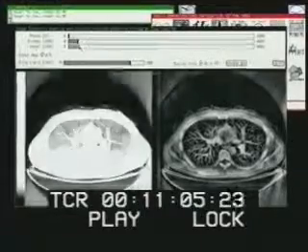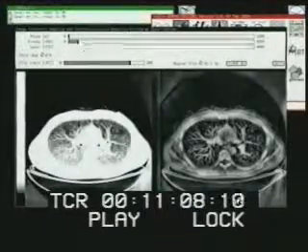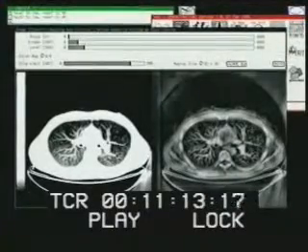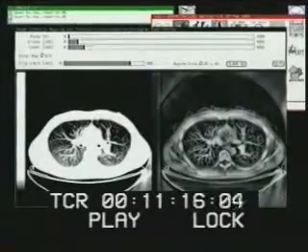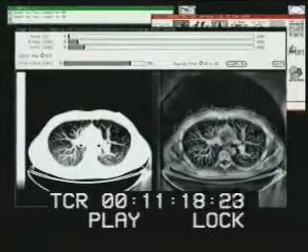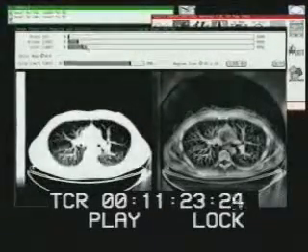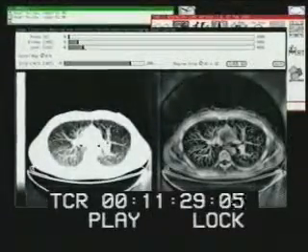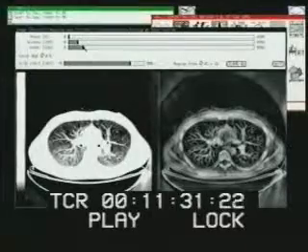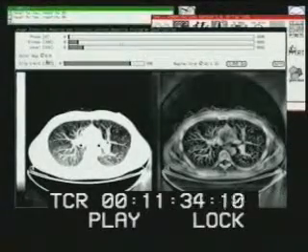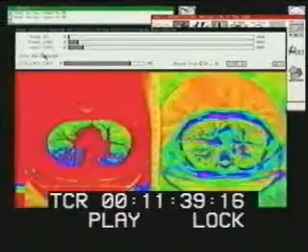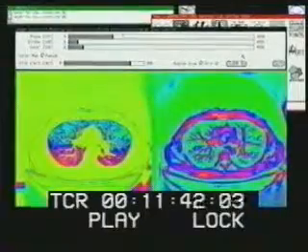on the left. The way we do intensity windowing is by storing the original image someplace in the frame buffer, reading the image, doing a lookup in our programmable lookup table, and then writing a new image out elsewhere in the frame buffer, and that's what's being displayed on the left of the screen. So this gives you a good idea of how fast the TAAC can read, process, and display an image. We can also use different color maps. This is a heated object color map, pseudocolor, etc.